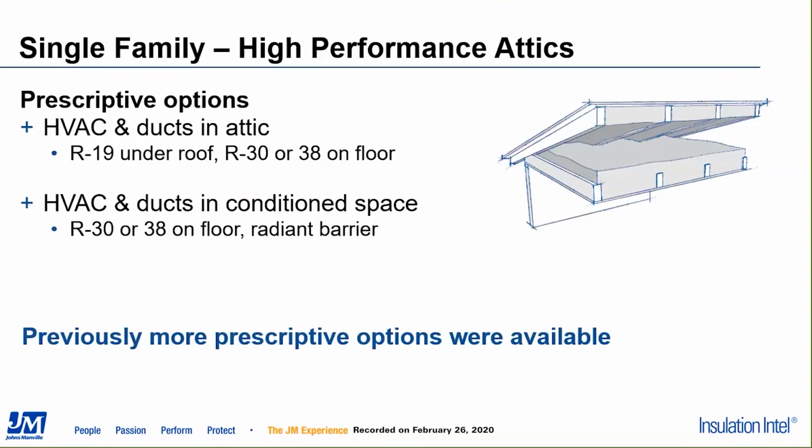If we're putting our ductwork in conditioned space, and that could be through a number of methods, right? We could bump down a little soffit where the ductwork is all going to go. The HVAC equipment could be in some sort of a closet. We could be using mini splits, right?